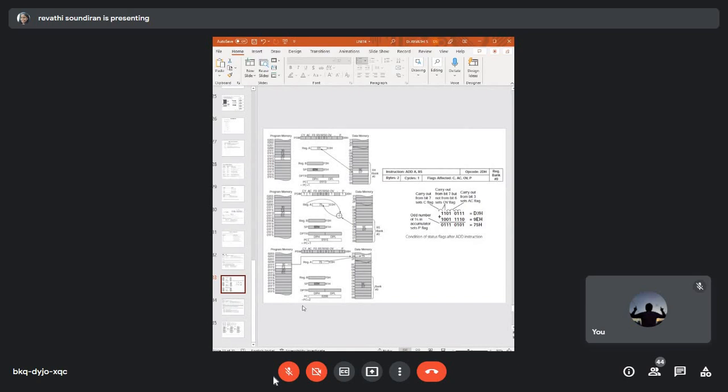Okay. So now you can see the flags remain as they are. The opcode for it is F5, and the memory location is taking the value 30. Now, being a move instruction, none of the flags will get affected. Whatever flags are set will remain set. So your program status word remains unchanged after the move instruction is executed.